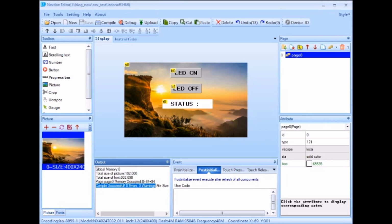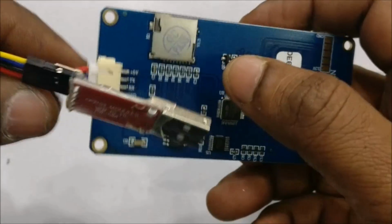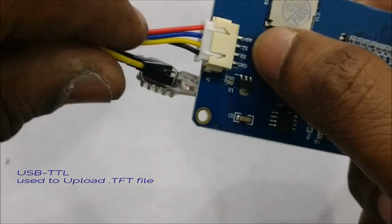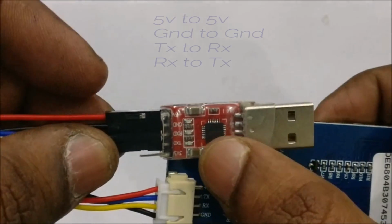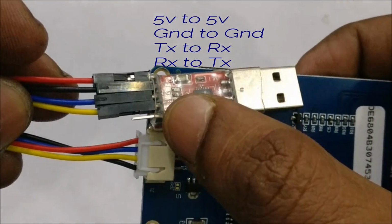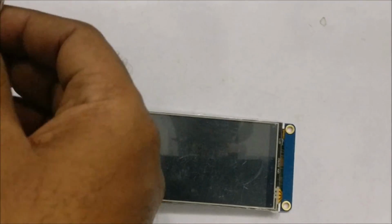Before clicking upload, we'll see the first method. First method is by using USB to TTL device. Here I am using USB to TTL built on CP2102. The connection between NEXTION display and USB to TTL is simple: 5 volt to 5 volt, ground to ground, TX to TX, and RX to RX. RX to TX. Reverse.